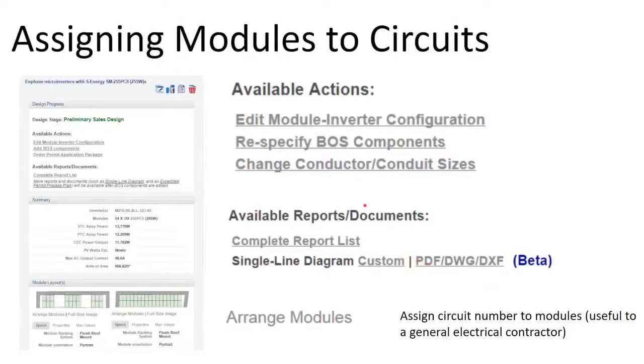But Solar Design Tool has a plethora of final design detail documentation, more than really any other software. It provides the most detailed out-of-the-box one line diagram, which is pretty impressive given that it's on the low end of price, with the caveat that its tools are really geared towards small residential projects, 4 circuits or less. In general, sometimes I'll model larger projects and then stitch them together in CAD afterwards.